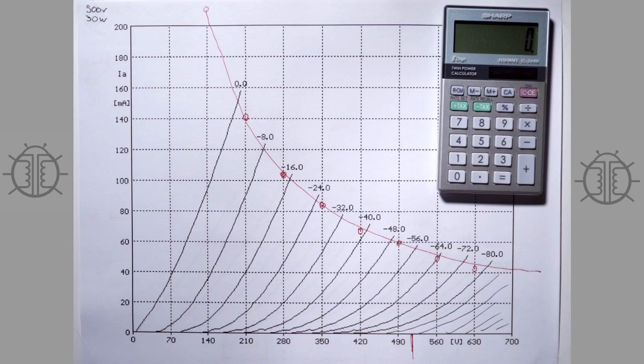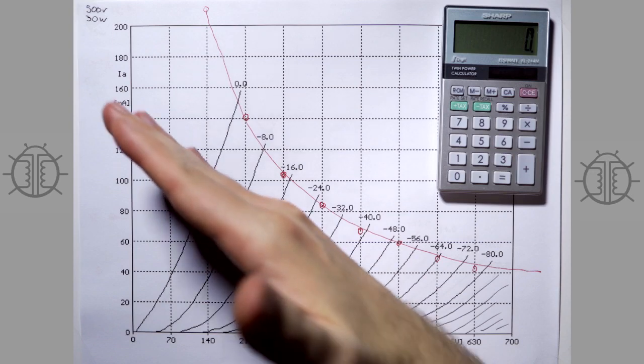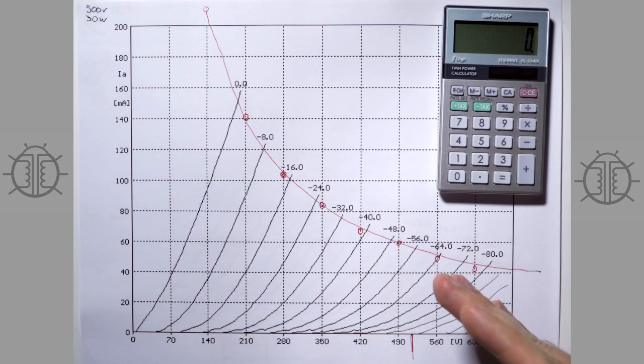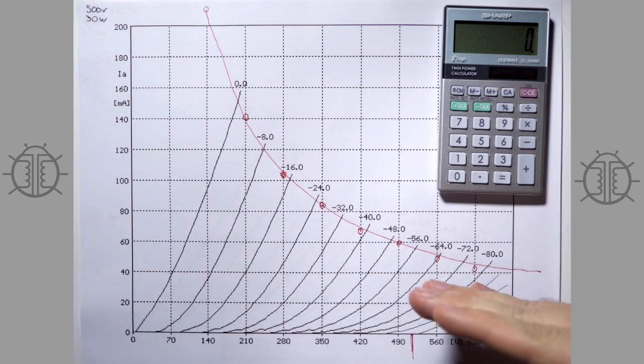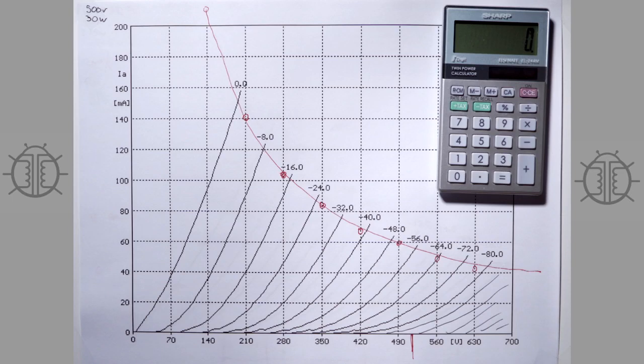I mean, it's still about power, but with an output stage, you're trying to actually drive a speaker with it or something like that. And so the way you develop power is, remember that power is a volt amp. And so you want to swing through as much voltage as you can, but you also want to swing through as much current as you can. So if you only were swinging through voltage, that would mean your load was infinity. Remember, like before, I should be using my load line.